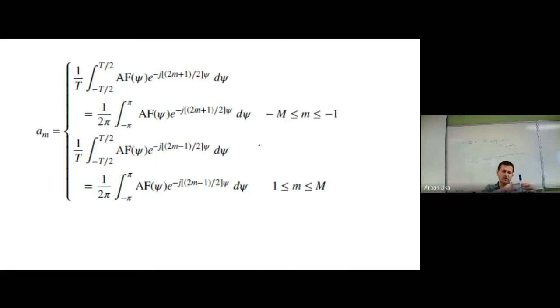Then we can calculate the Fourier transform of this current, and we find what is the array factor up there in the space. So with the Fourier domain, we are obtaining some information regarding the possible directions of the k space. What we should not forget at this stage is the following. In the wave equations, you remember that we have e to the power jkx and e to the power j omega t. Now, k and x are reciprocals of each other. x is the real domain, k is the complex domain.